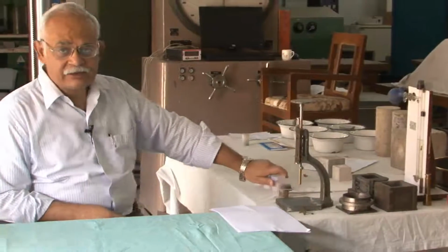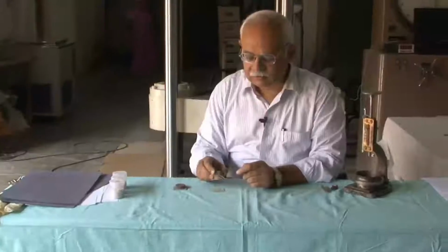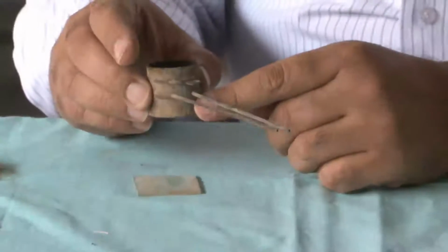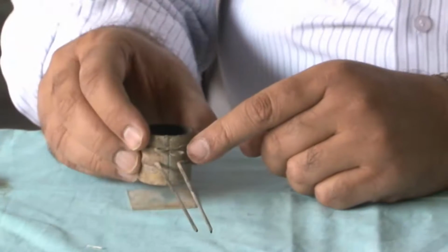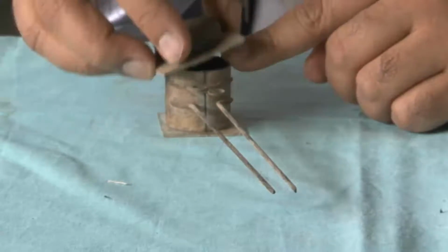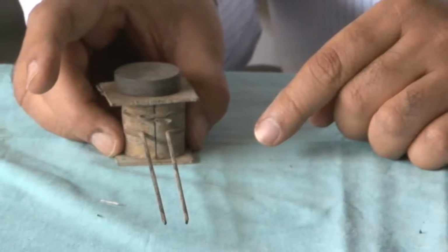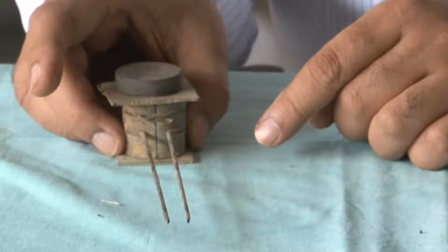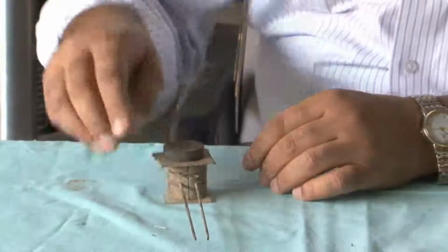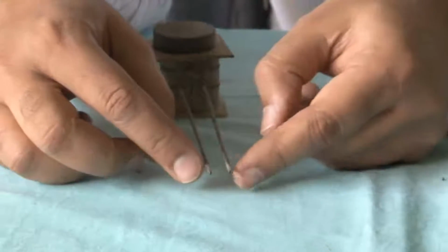When it comes to testing the strength of cement, we use mortar samples. This apparatus is used to determine the soundness of cement. What we do is to put a cement paste sample in this, cover it and put this entire assembly in water, have it at a certain temperature and expose it for a certain period of time, and the measurement taken is the distance between these 2 ends of the fork.